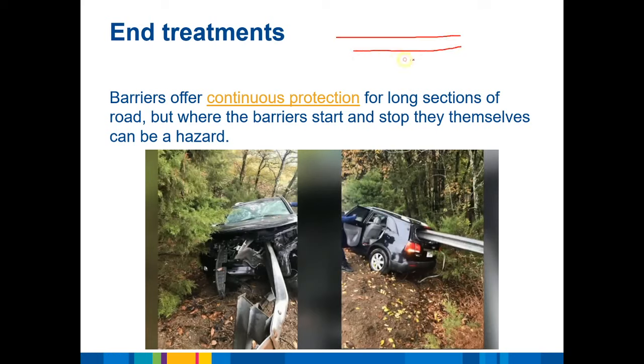You've got the barrier, and then the end is almost a little fishtail. There's really nothing to stop that spearing through the vehicle. So we need to make sure that where the barriers start and stop, the barrier itself is not made to be a hazard.